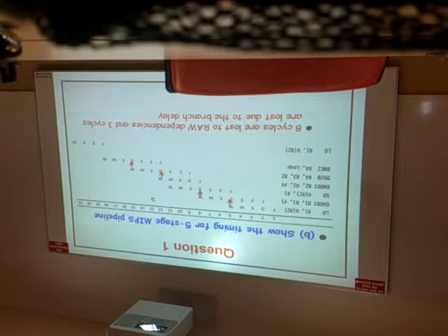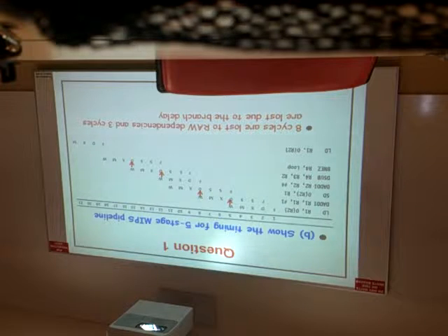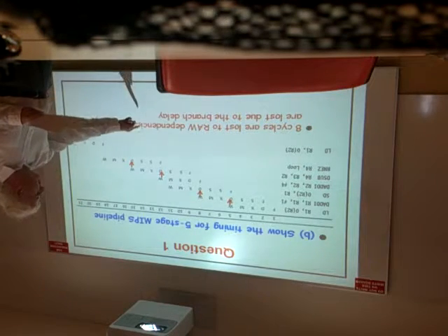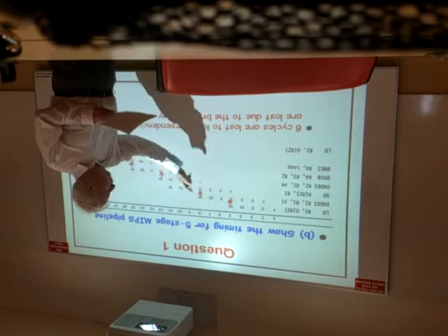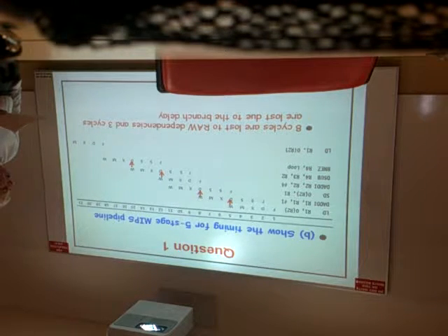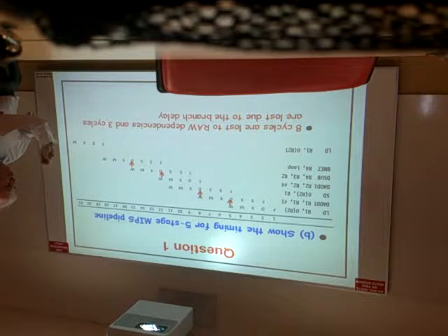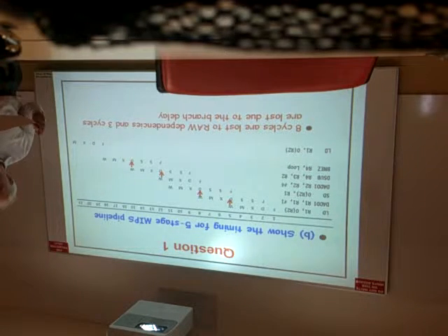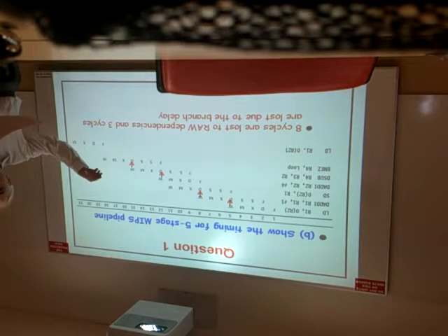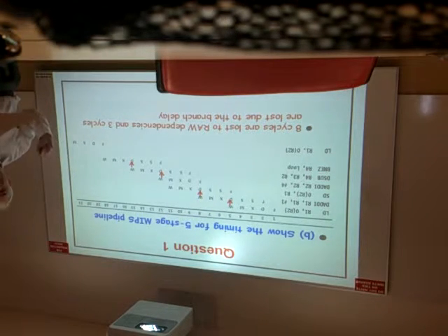S is store, so S is in the execute stage. For the read after write dependencies, we lose 8 cycles altogether. For this pipeline, it's only the read after write dependencies which require the stalls.